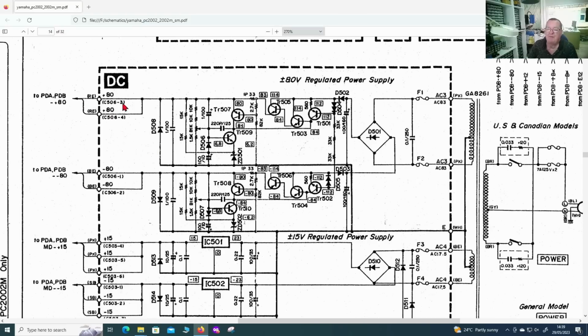But one of the amplifiers is missing its voltage supply, so one channel would work, one wouldn't work, but there was no protection anymore. What I found then wasn't a short. It was 75 ohms, almost 80 ohms to ground on one side, one channel. Now, you may think 80 ohms isn't anything like a short. I mean, 80 ohms is a fair bit of resistance, yeah?